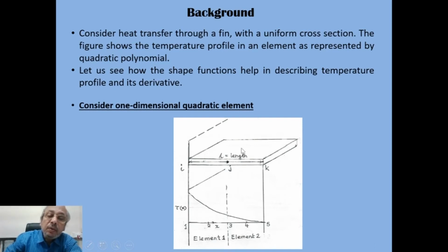So basically, it cools the metal or the body of interest, and its temperature profile is basically parabolic or non-linear, and it varies from base to the tip, and basically the fin loses heat to the local ambience, and that is how the temperature varies from a value, say Ti, to Tk through a parabolic variation.